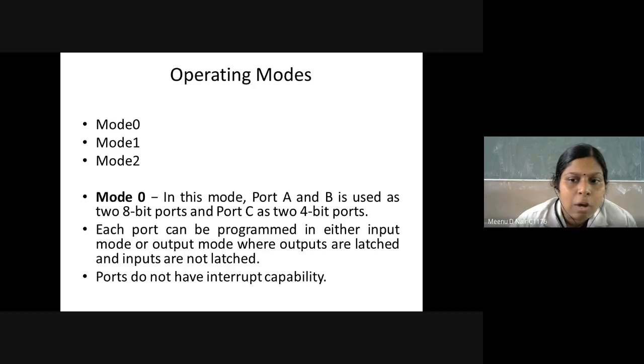Then outputs are latched and inputs are not latched. Latched means that once the register is completely filled with the data, if you change the input signals, the output is not going to change. So output is latched, it is not fluctuating. Once you store the data, it will stay there. And input is not latched, so whatever input comes, the input is going to change.